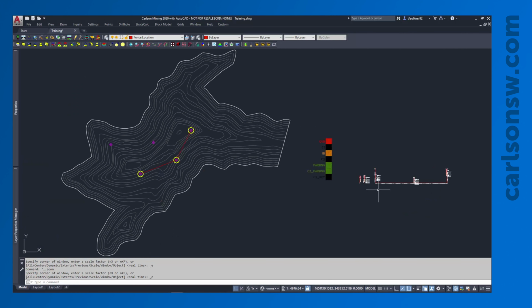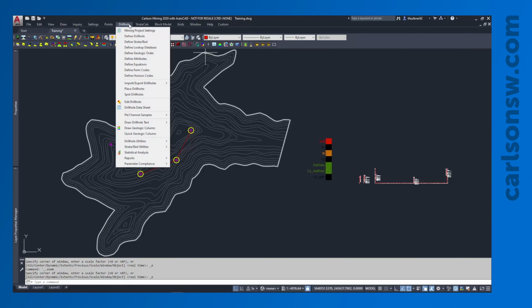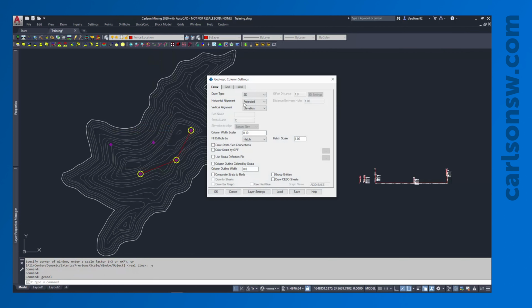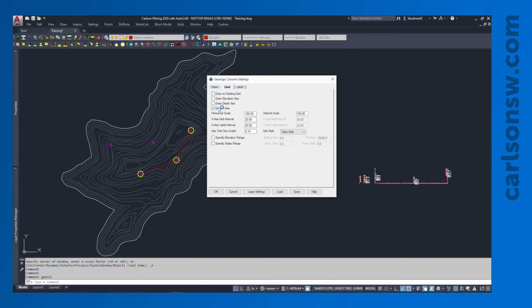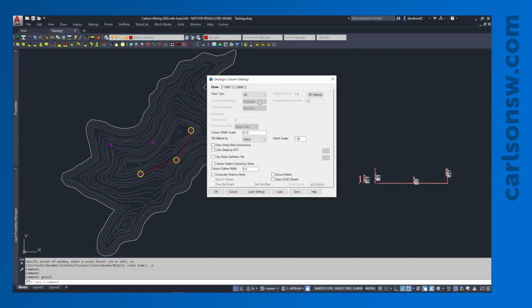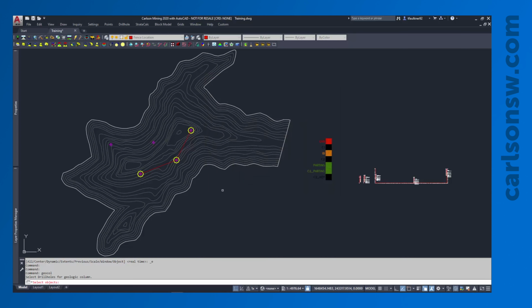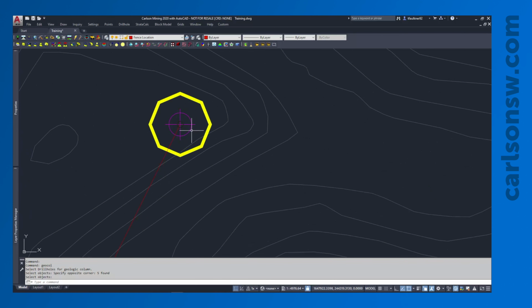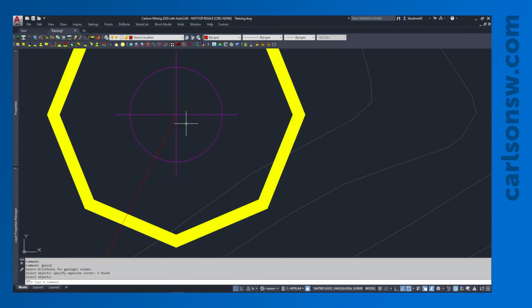Now I'm going to show one last way to draw these drill holes, and that's going to be in 3D. So this time I'm going to go back to Draw Geologic Column, and this time I'm going to change the draw type to 3D. I am going to go to the grid and say I don't want to worry about drawing any of these axes. It's fine. And we're just going to click OK. Pick all the drill holes. Click OK.